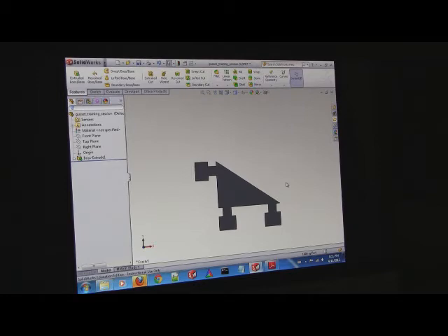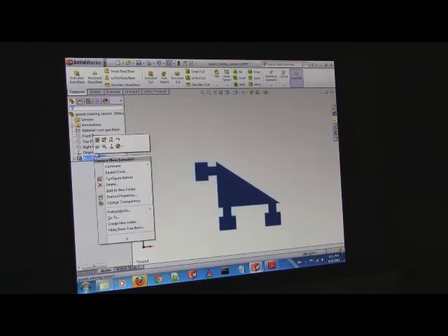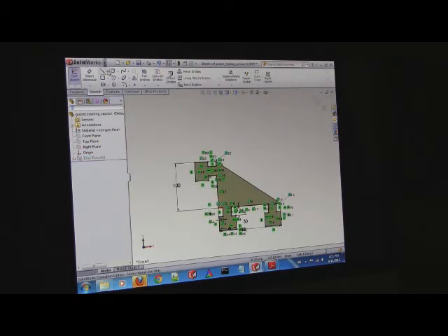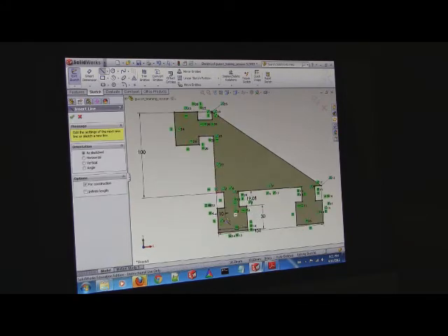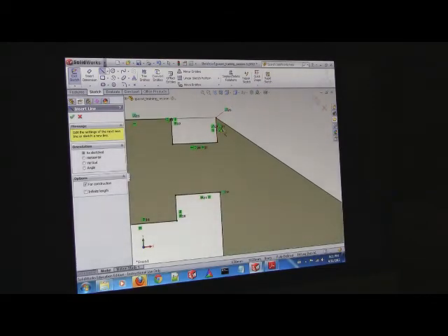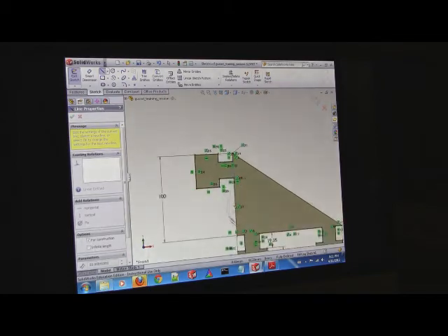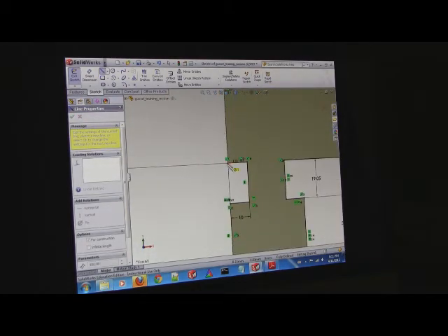We good? Okay, so go back and edit that sketch. Now watch my screen for a sec, please. I'm going to take a construction line and put it in the middle of this line. You see how it snaps to? Except that's not what I want. What I want to do is take this and mirror it about the center of this image, about the center of that 100 thing. So I'm going to take a construction line and put one end at the top and one end here.